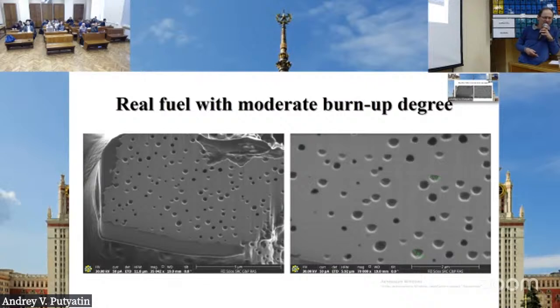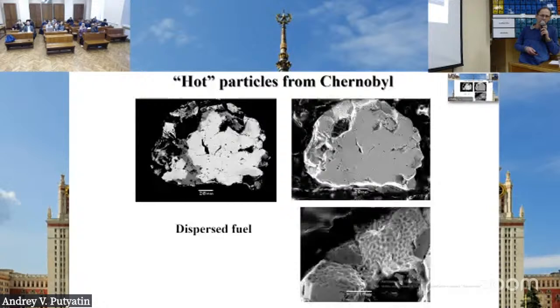And these white dots, I actually noticed some contamination, but this is a very fresh slice made in situ in the electron microscope, so contamination was impossible. So these small particles are just particles of the so-called five-element phase or epsilon phase, which consist of platinum group elements plus molybdenum, technetium, and so on. We'll come to them somewhat later. So this is a real fuel which underwent operation in the reactor, but to quite a moderate degree of burn-up.